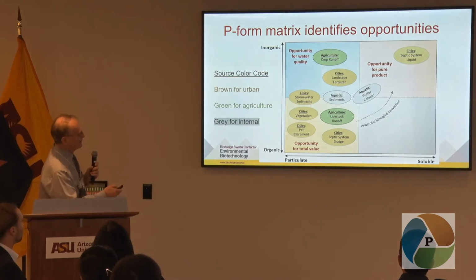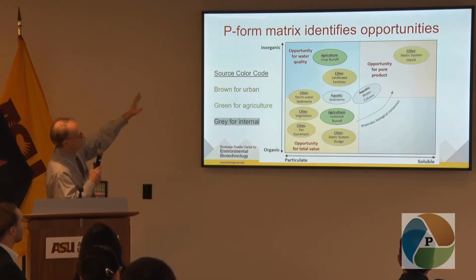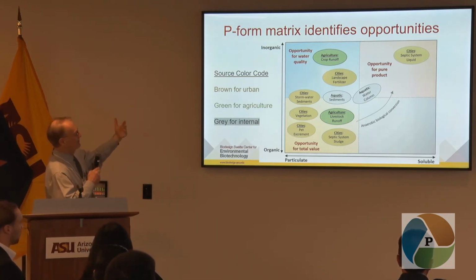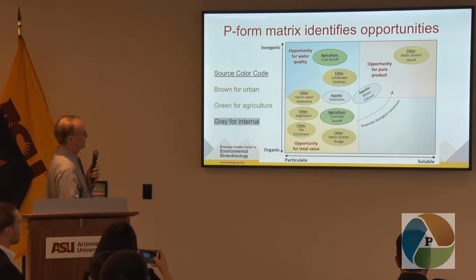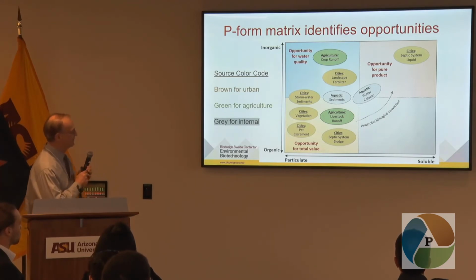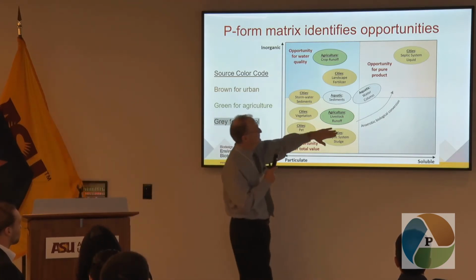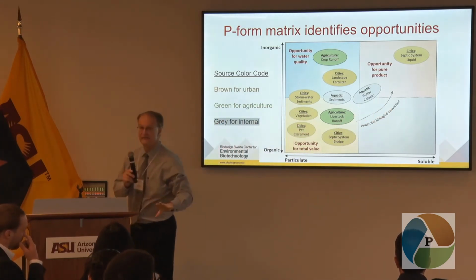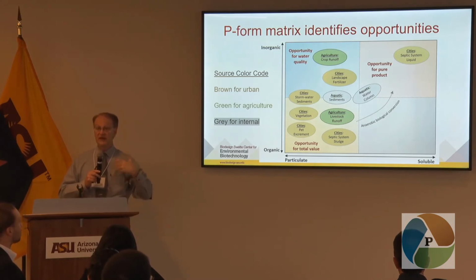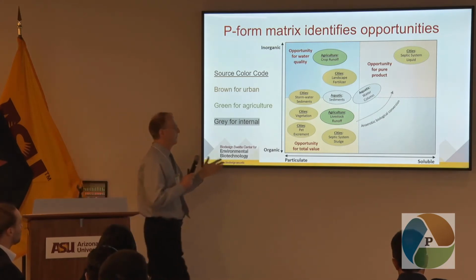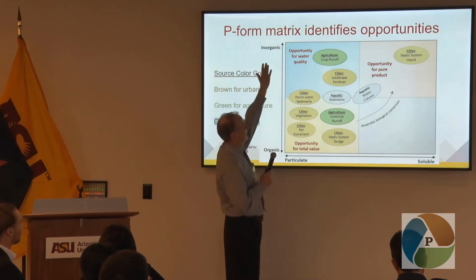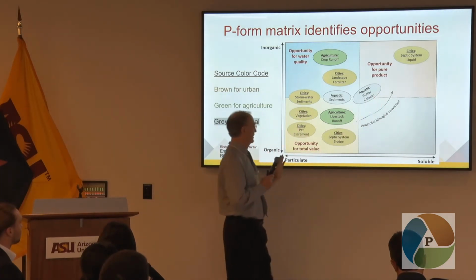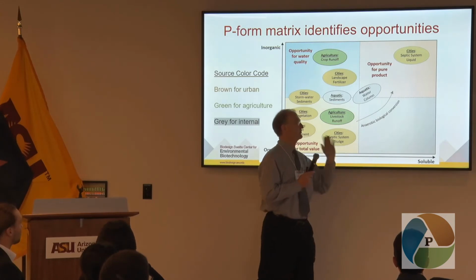And you can see there's a wide spectrum on the left side of the graph. So there's a tremendous number of different sources that are mostly particulate. They're on the left side of the graph. There's not much on the right side of the graph over there. Although one of the important things is that you've got this little arrow here, anaerobic biological conversion. This is what I just talked about a few minutes ago. So when you're doing the anaerobic biological conversion, you're converting from organic to inorganic. The arrow goes up, and you're converting from mainly particulate to soluble, and that's going from left to right.